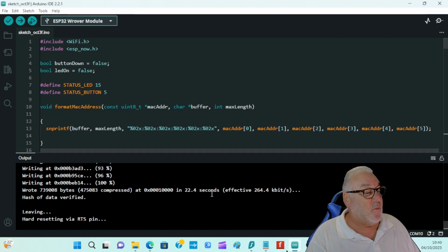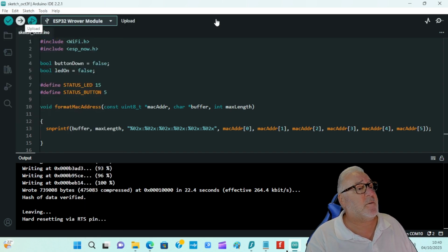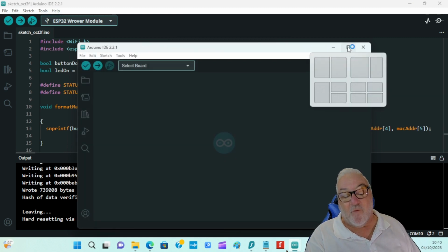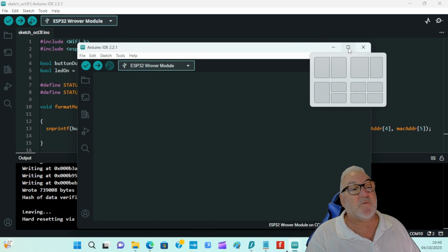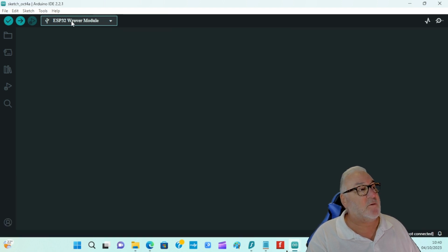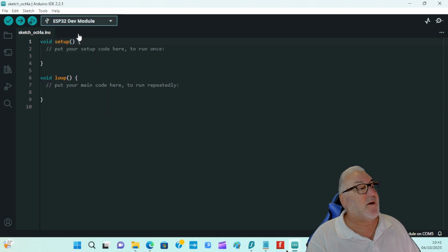And then what I'll do is I'm going to go File, New Sketch, open a new sketch. Just showing you, I've already uploaded it to all of my ESP32s, but I'm just going to show you how to do it. So now what you want to do, change your board. You want to change your board to Dev module, on Com 5.